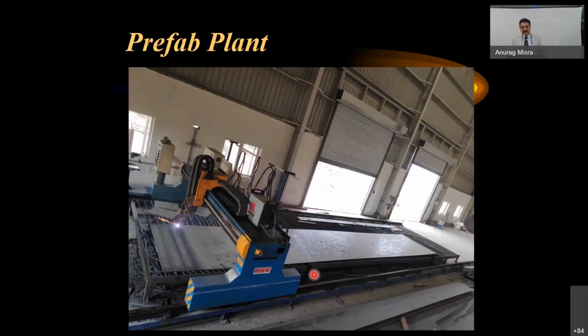Now, very quickly, I would scan through how they are created. Now, when we are talking about the steel construction, it is the normal welding process or cutting process. This I have taken from one of the plants, which is your steel plates. That's the maximum size normally which you can handle, 12 meter. So you do the nesting with the software, and whatever components are required, the CNC plasma cutting machine, you simply need to feed the drawing, and this is now creating these stiffeners.